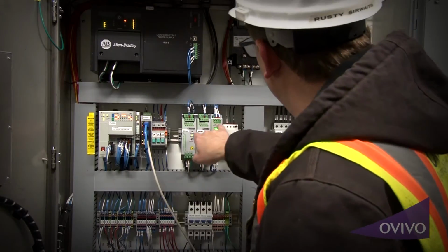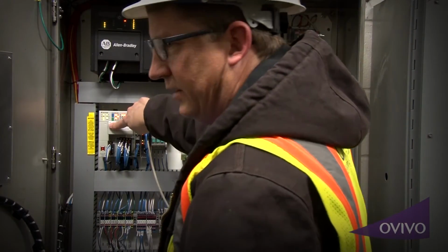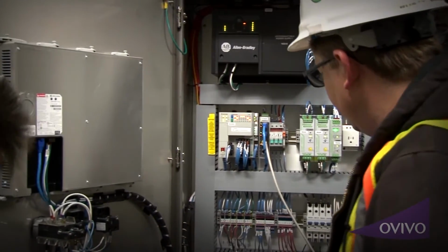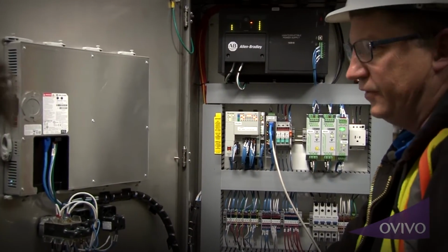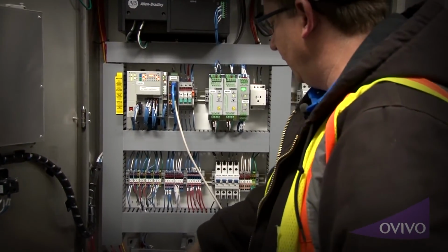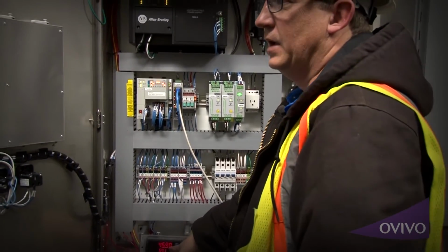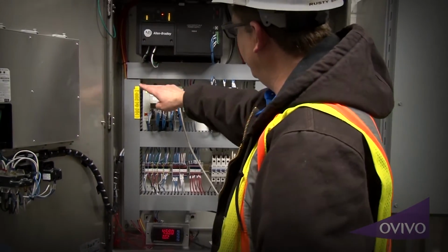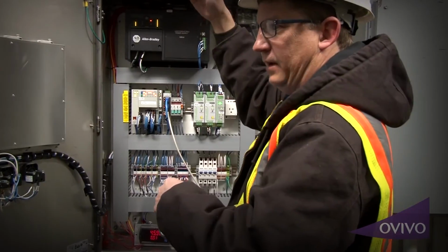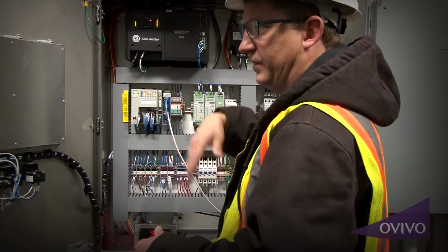These would be your sensors. This is your PLC, this is your computer. Your HMI is back up over here. These are your switches. This right here is your level sensor. This is taking the 0 to 5 volts that's coming from your load cell and converting it into a 4 to 20 signal output. And then this 4 to 20 goes into the PLC, and that 4 would be your full, 20 would be your empty, and then it scales up between that.